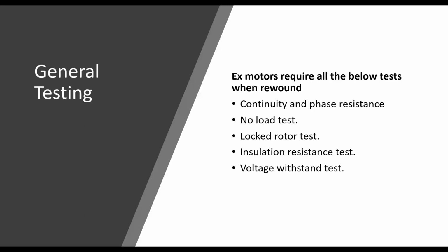So if you can't perform a locked rotor test, put it in your paperwork. These are only tests that should be done. Should, not must. But you need to put in your paperwork the tests that have been done and the tests that have not been done. Because the user could look at the standard and quite happily assume that all of those tests have been carried out before they put it back on their system, on their plant to start doing the job. Okay. Again, insulation test and a voltage withstand test.